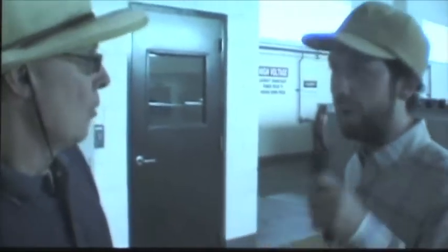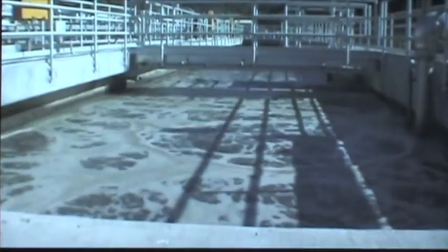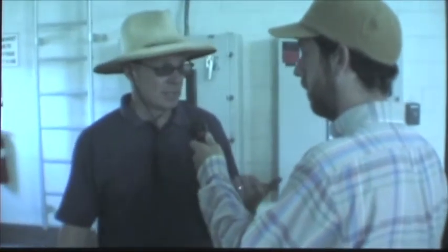Digesting? Yeah. Anaerobic. This is from the aerobic. Remember, it comes from the primaries. This is not primary sludge. This is sludge that comes from the aerobic process, from those aerated tanks. It essentially gets thickened at the bottom of those secondary clarifiers, then it gets pumped over here and thickened a little bit more, then it's pumped directly into the digesters.